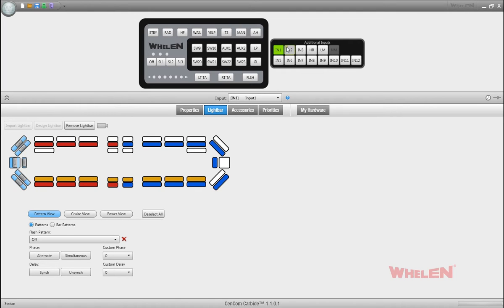You can also tie into the trunk signal and turn off warning LEDs in the rear of the light bar, letting you see clearly into the trunk. You can also tie into the park signal and set flashing takedowns to steady when shifting from drive to park. You can also tie into the brake signal, and whenever you step on the brake pedal you can steady warning LEDs in the rear of the light bar, letting other vehicles know in a pursuit that you are slowing down.